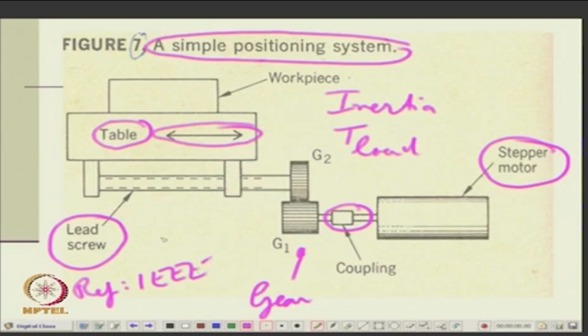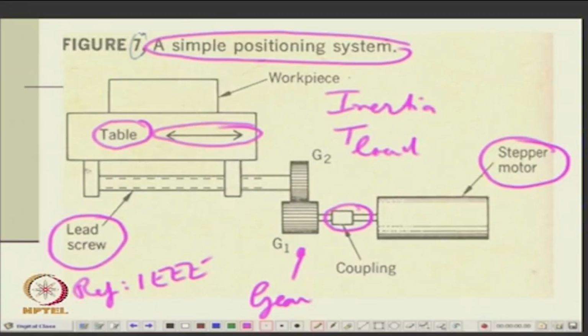He has given this example that there is the inertia of the cylinder, okay. There is this acceleration, after all when it accelerates what should be the torque, etc. And what will be the total T inertia, okay. So these are calculated based on the parameters of the mechanical system, you need to have all of them to find out what is the inertia, what is the load torque.